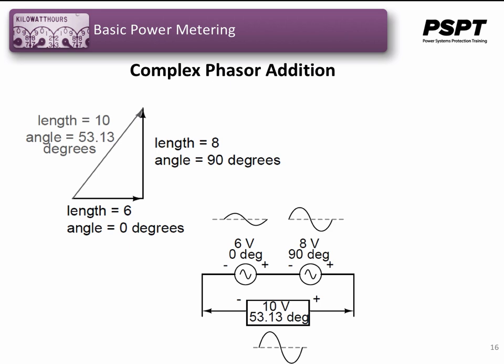However, adding and subtracting of complex numbers is much easier if you're able to convert to and from polar and rectangular notation, because the addition and subtraction of phasors in rectangular notation is very easy, and the multiplication and division of phasors in polar notation is the easiest form. So what you want to do is add using rectangular formats, and multiply using polar formatting.